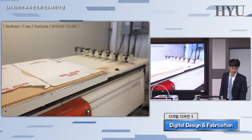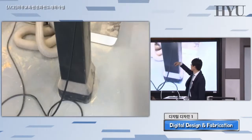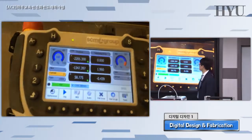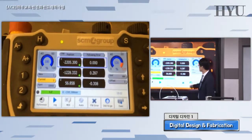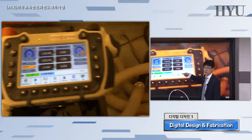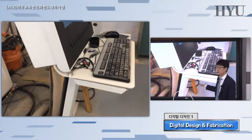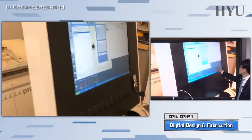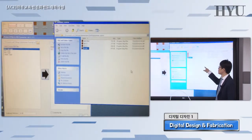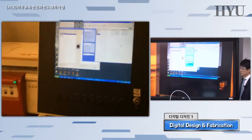And if you see, there are a bunch of different types of drills. The machine automatically replaces those drills according to the operation. This is the control. As you see, XYZ coordinate system, okay? Very precise XYZ location controlled by computers. And this is the software to simply import the geometry for making using the CNC machine.